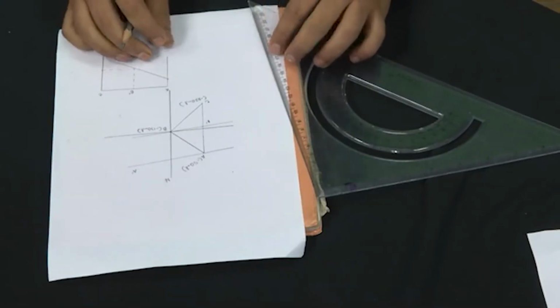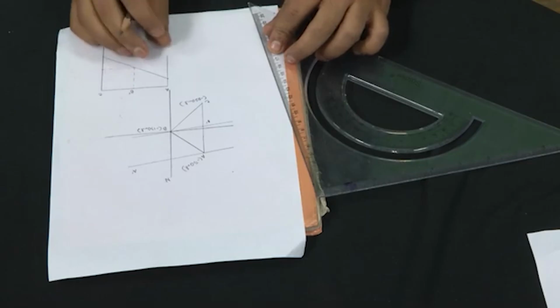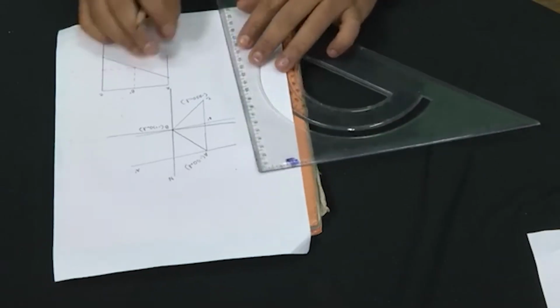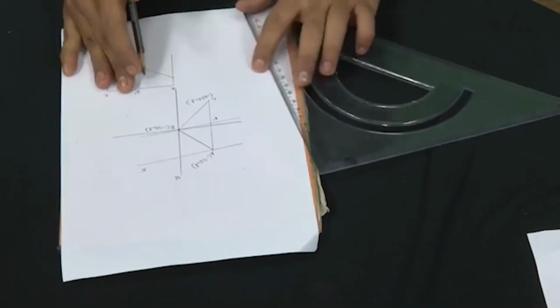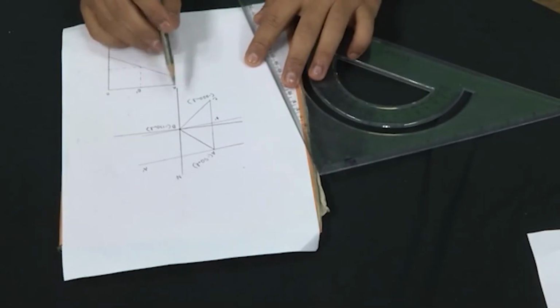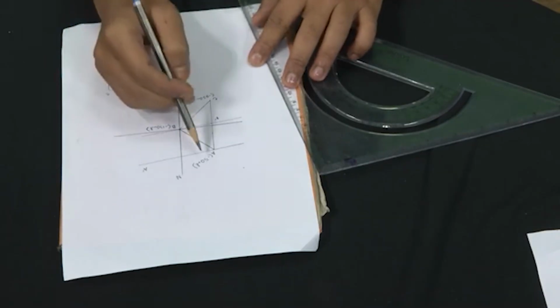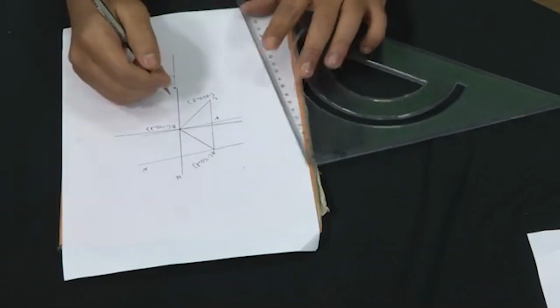So, now basically what we have is the strike lines of two depths of the ore body, one A dash, which is the strike line of the ore body corresponding to minus 50 meters depth, and another is B dash, which is the strike line of the ore body corresponding to minus 130 meter depth. Clearly minus 130 meter is below minus 50 meters. So, the bed is dipping towards this direction.